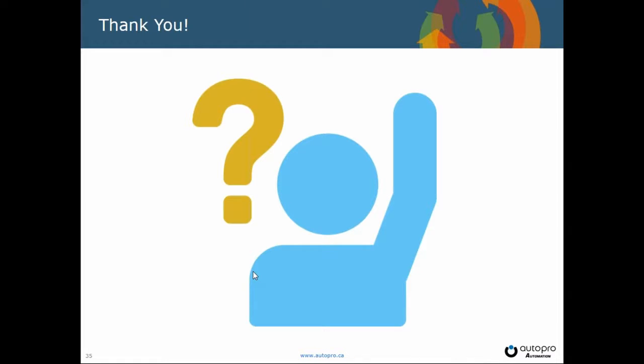Throughout the presentation, the examples of a CHAZOP recommendation show the need to install a redundant item. Would it be safe to assume that the current thought is to install a complete redundant system that could prove very costly? You don't need redundancy everywhere, and it's true. What we're trying to identify is if there's a critical area, for example a process looking at the feed into your facility. Without that, you'd be down, with lost time and all of that.